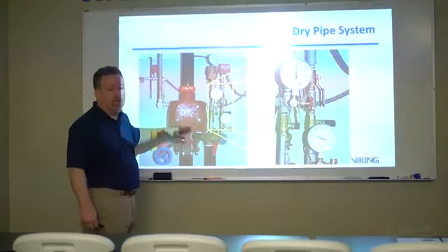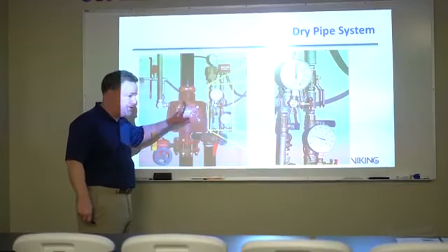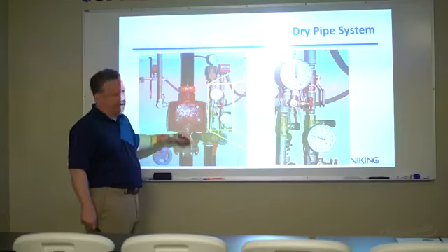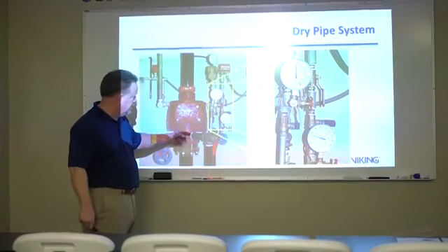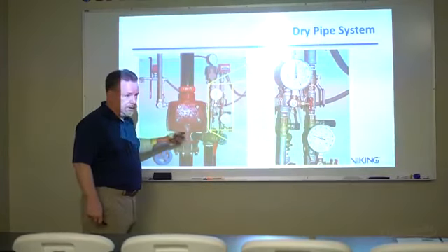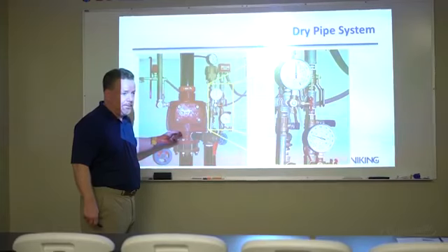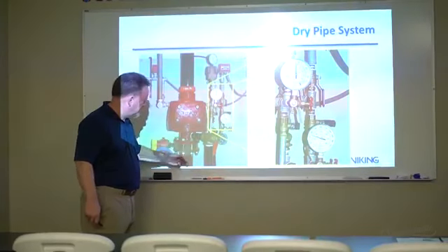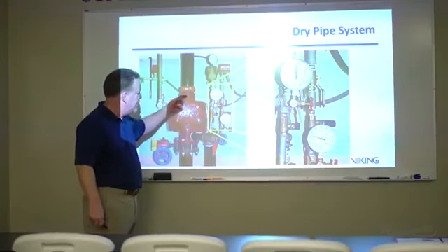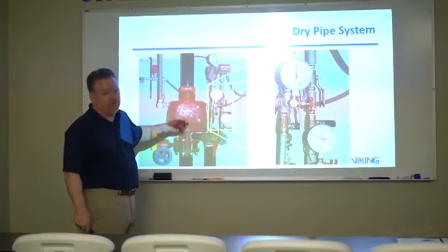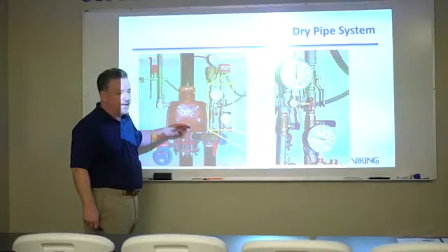It's a 6-to-1 ratio or a 5-to-1 ratio, something along those lines. If I have 100 psi of water pressure coming up underneath, I should be able to hold that closed with a 5-to-1 ratio, about 20 psi above.